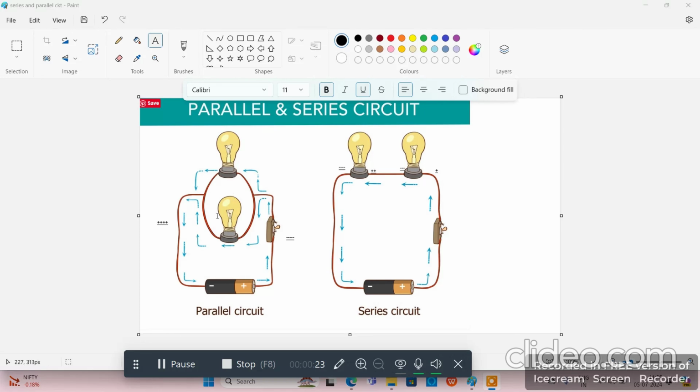For example, here I mark negatives here. For example, this is my LED 1 and this is my LED 2. So in LED 1, negative should be connected, and LED 2 also negative should be connected to the supply negative, and positive. Since I use a switch here, after the switch, since this switch is connected with the battery, this connection is positive only. And in the LEDs also, these two connections will be positives only. So positives we have to connect together.